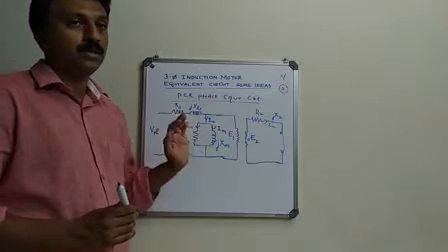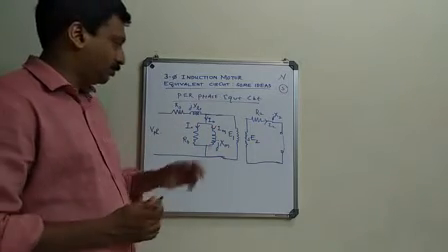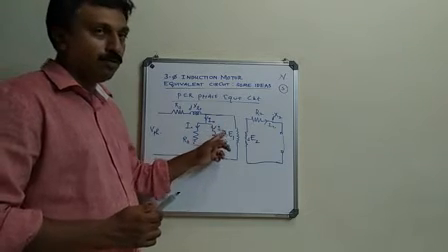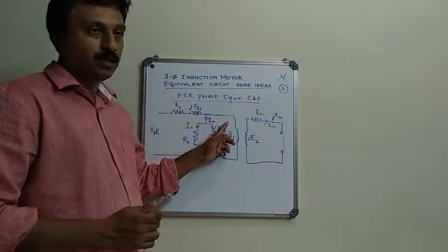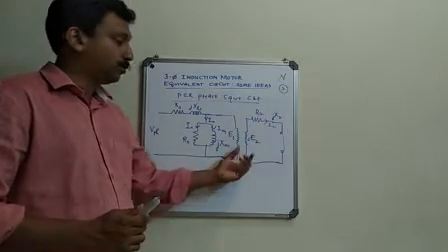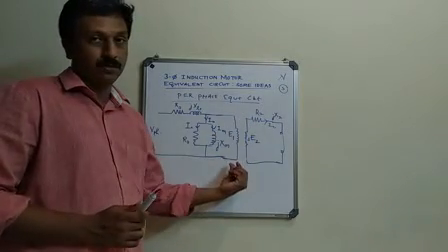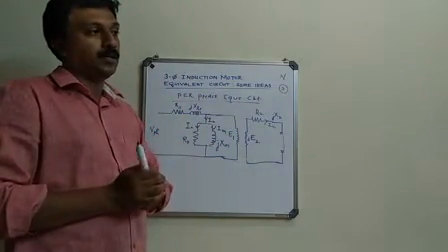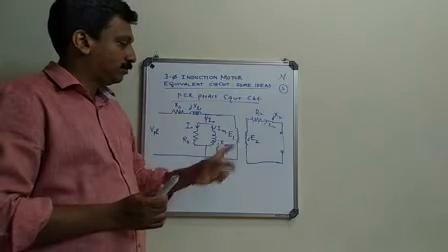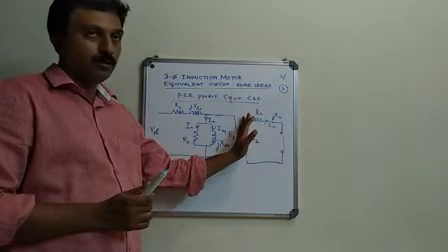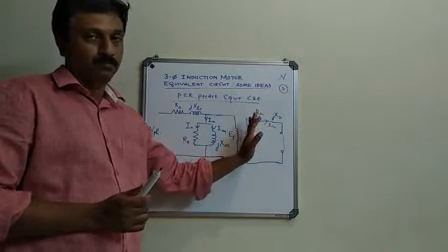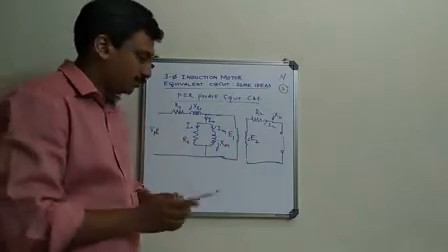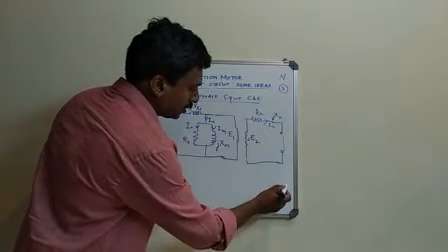You cannot do it in the case of an induction motor because of the relatively high magnetizing current that is required, because of the air gap presence between the stator and the rotor. Here, there will be some part that is iron and some part that is air. So the magnetic circuit involves an air gap. So that will create this extra.